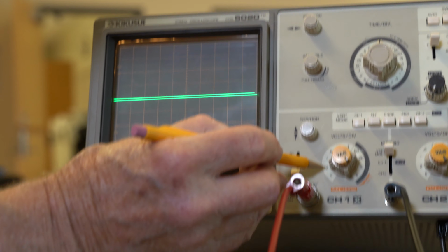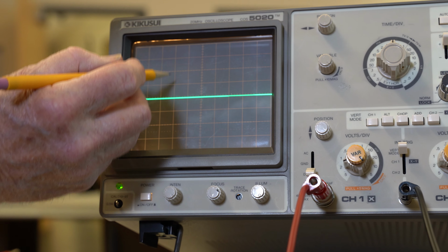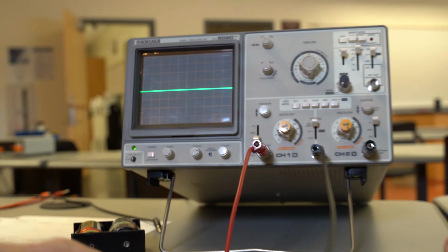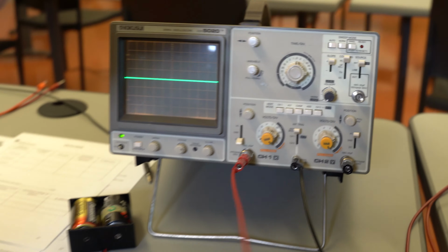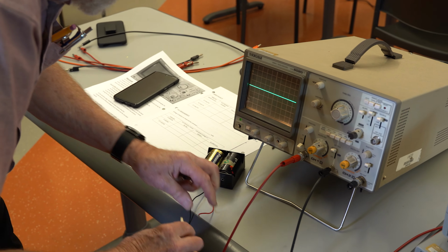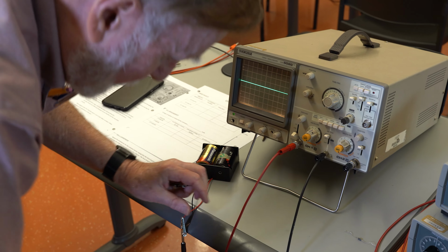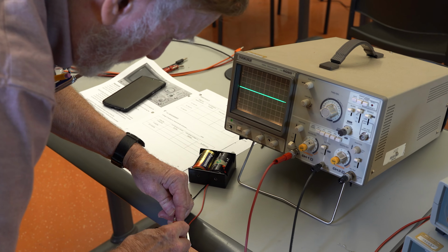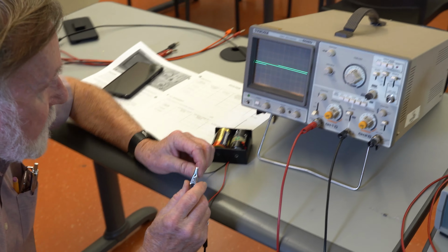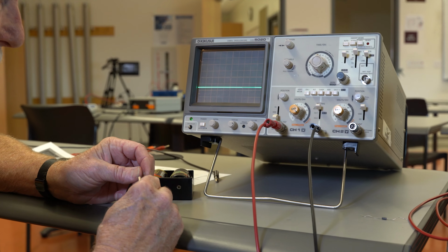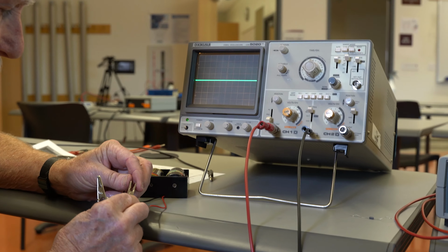Now this says 2, so that means 2 volts for each division. So let me connect this to the voltmeter, and we'll see how far it actually goes. And just clip this to, I've got 2 D cells here. Theoretically it should be around 3 volts, but they're kind of old batteries, so it'll probably be a little bit less. So here I go. I'm going to connect the voltage input from the 2 batteries, and I like it to go up so we could be a little bit more intuitive.